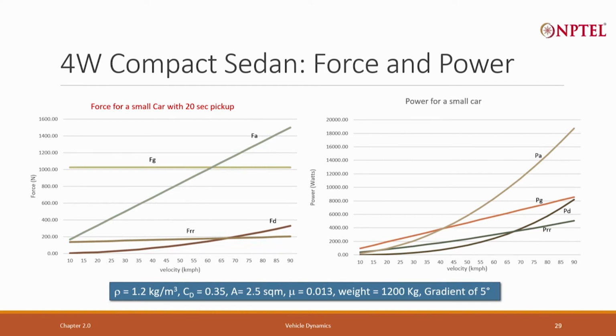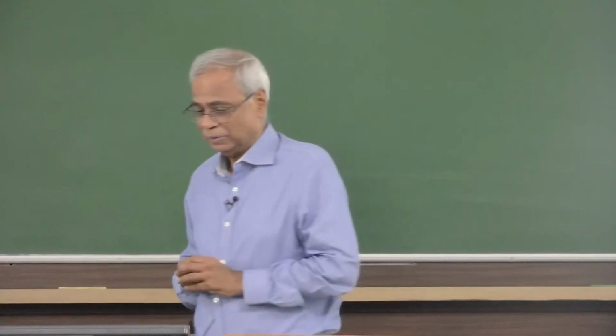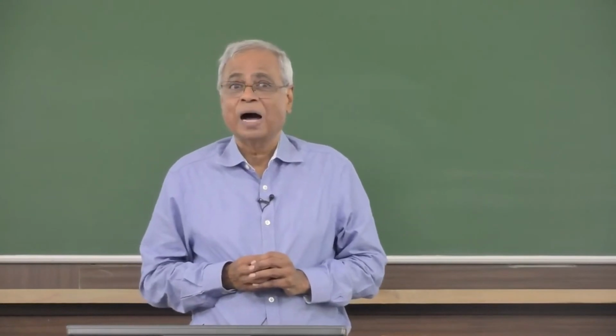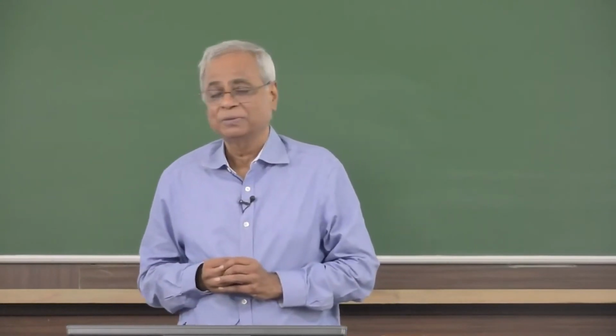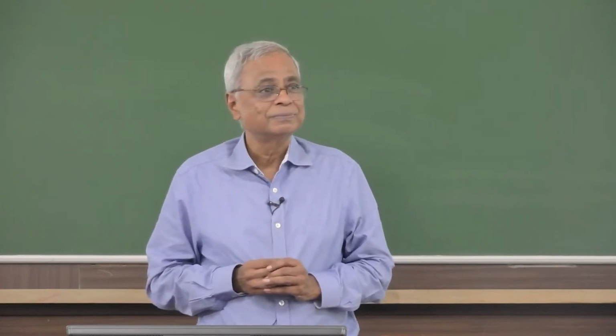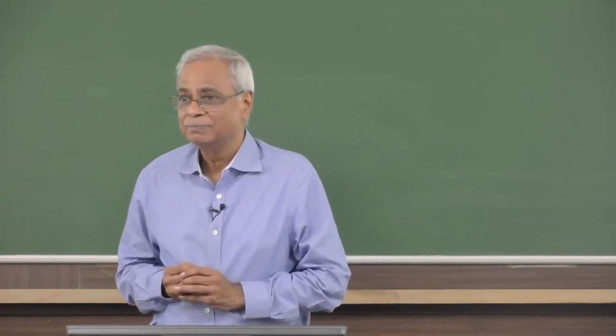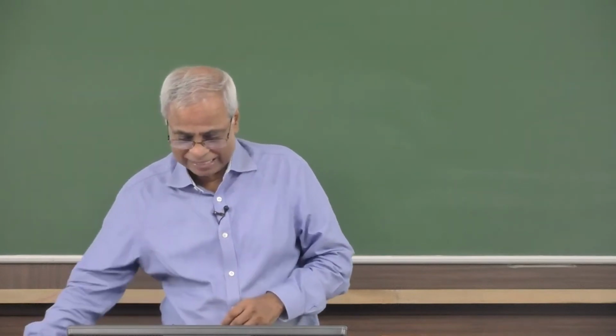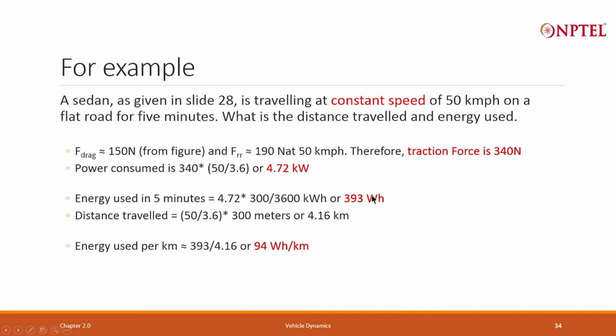And as I compute the energy required, assuming R equal to 1, 100% regeneration, what will be the energy required? Can someone tell me? 393 watt-hour. It is exactly the same, 393 watt-hour. Why? Whatever energy I spent while accelerating, I am recovering during deceleration, because R is 1, but in reality R is not 1.